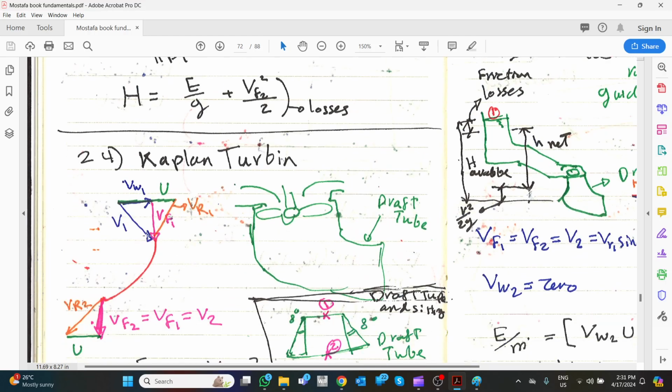And the velocity diagram, we can write it like this, because we know the flow is going like this and going out. So it goes in the plate like this, goes out like this. So we know that the relative velocity is vertical, but V is not vertical. So we have a whirling velocity, and because we know that for a certain slice of the water going in and out at the same radius, u in and u out are constant.